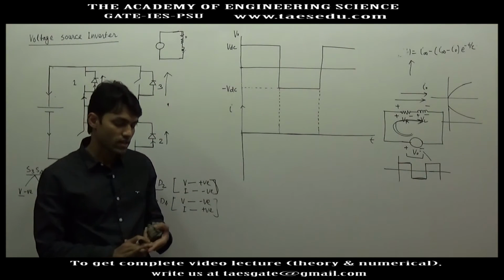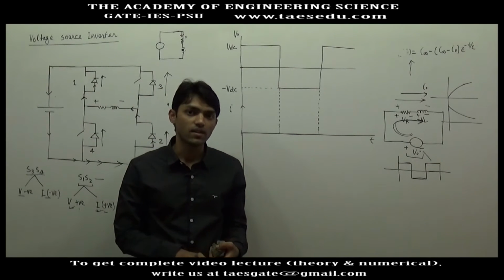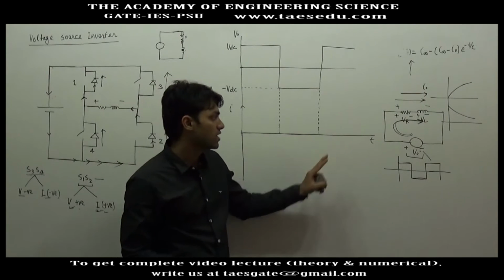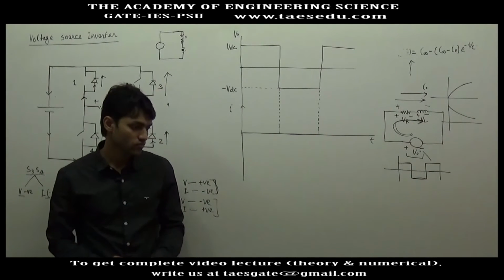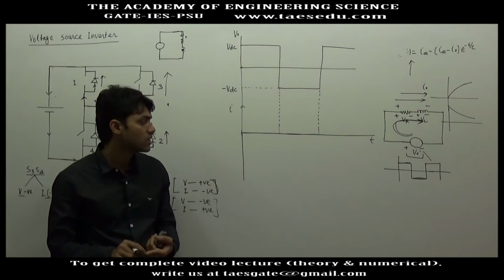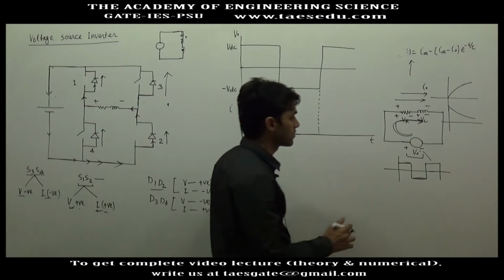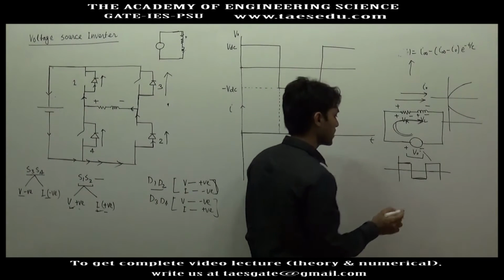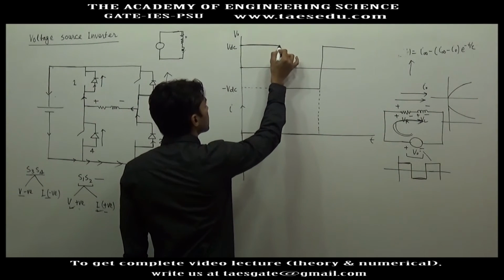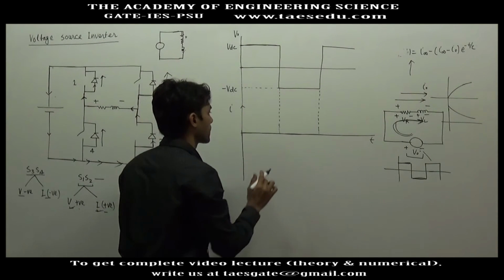So you will make such a graph of current that the positive area must equal the negative area to get the average value as 0. Okay, so we have to make positive and negative area equal. And we also have this information that whenever voltage is positive, current will rise. So in this interval we have positive voltage, so in this interval current has to rise.